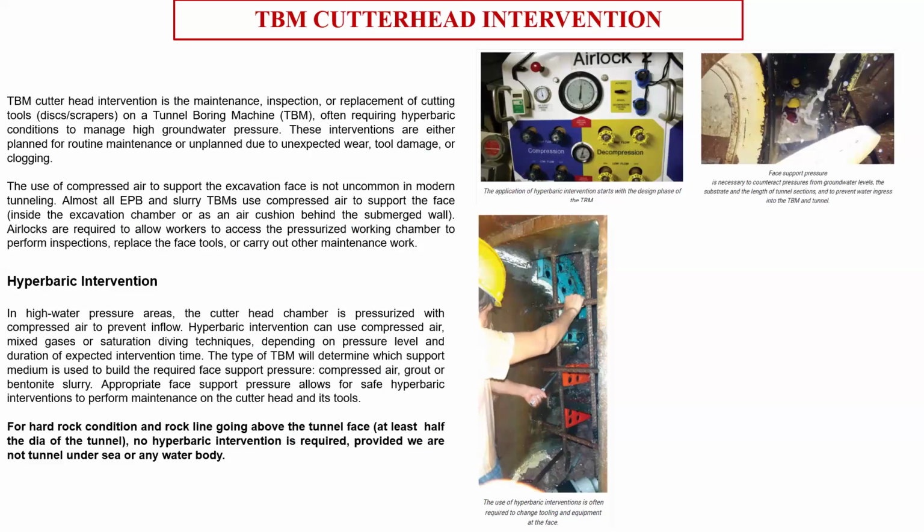So during the intervention, you have to park the TBM. So the TBM will be stopped. If you park the TBM below a very dense residential or densely populated area, where there are lots of structures, you have to ensure certain precautionary measures so that the face pressure is maintained and there is no ground settlement, and the structures lying above the ground are stable. So mostly we try to do this intervention in open ground. We do not do intervention in a dense residential area, or where there is a very soft ground condition.